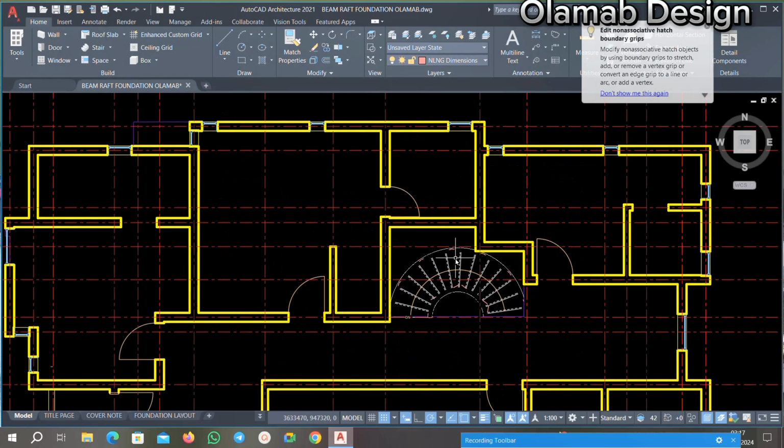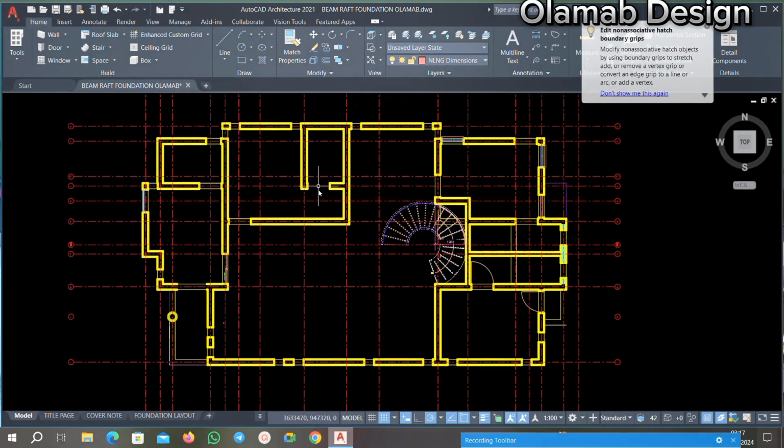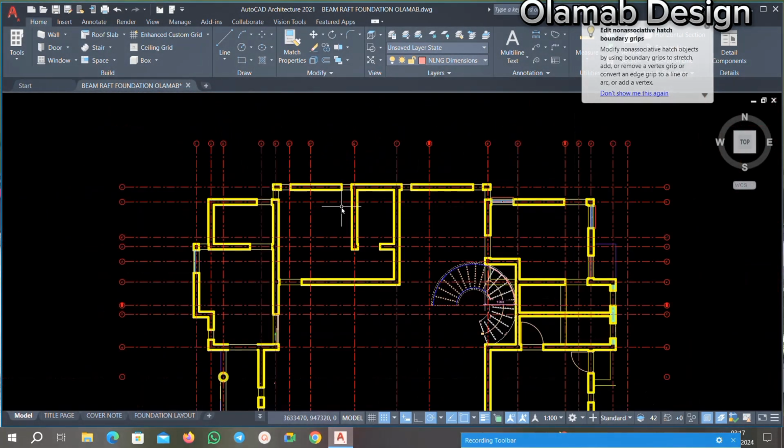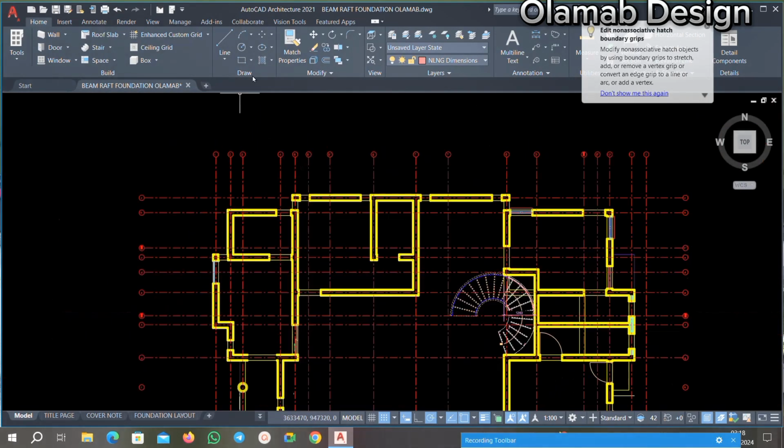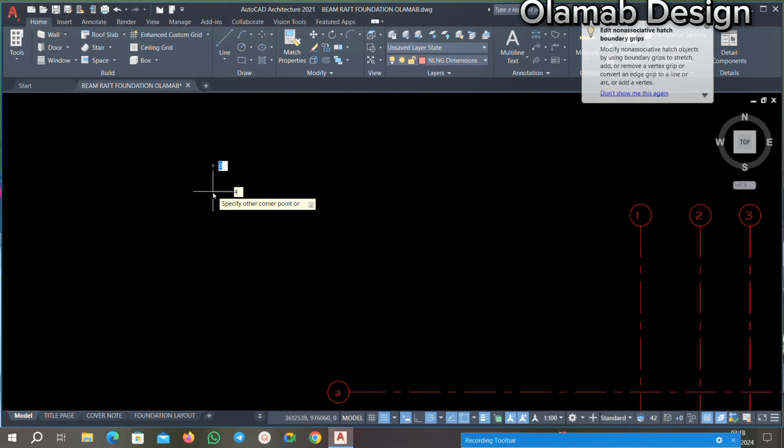Okay. So what I'm going to do now is go back to my ground floor, and I will make sure that I pick this rectangle tool, and I will draw a rectangle. I will draw a column of 225, press my tab by 450, and hit enter.